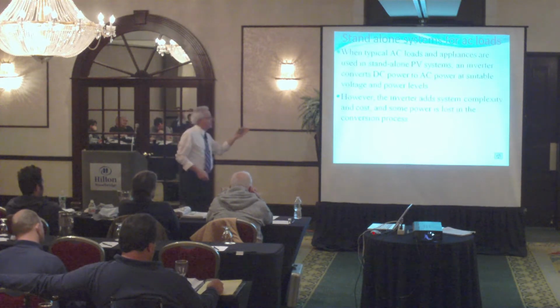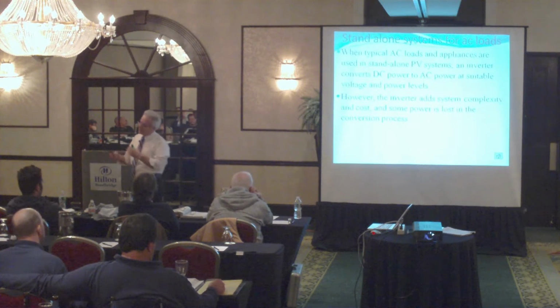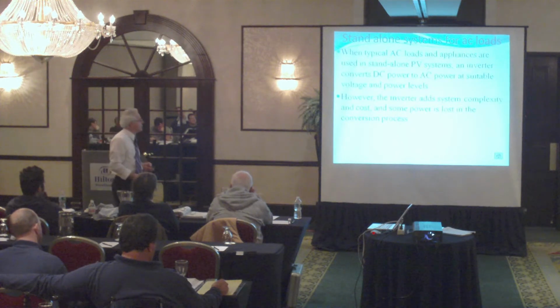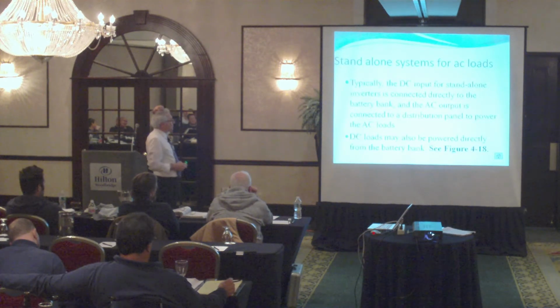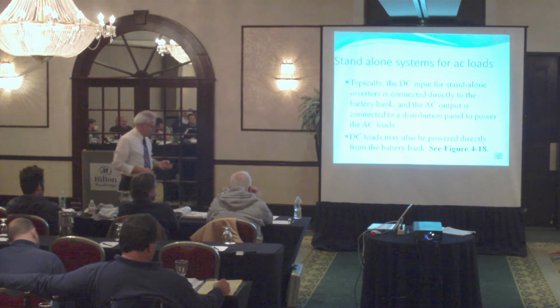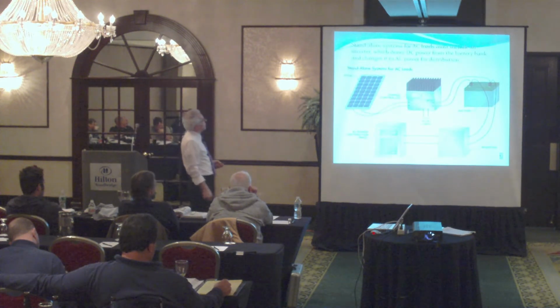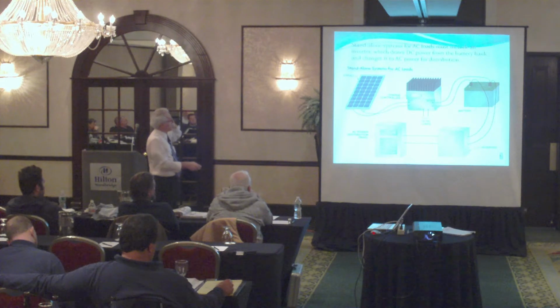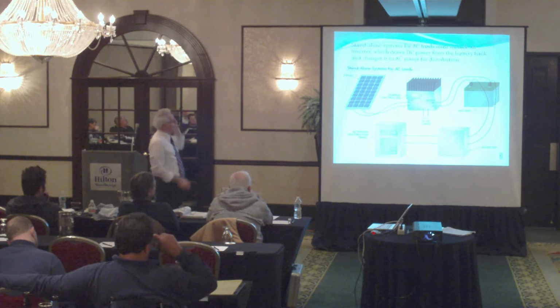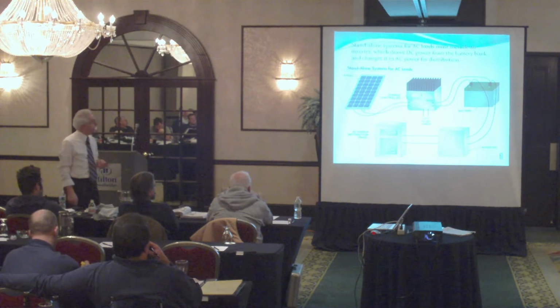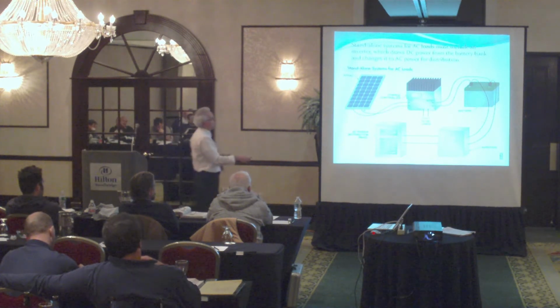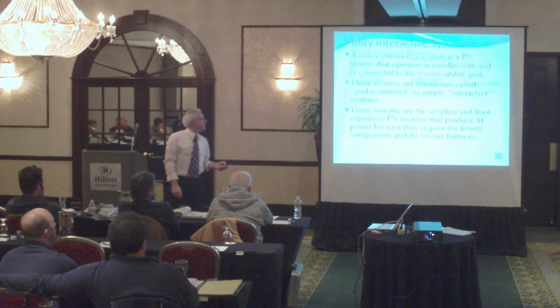Once you do that, you have a conversion process, so you have to consider the losses associated with the inverter. Look at this one, a typical configuration for that. This is your charge controller for the battery. Then from the battery, you take the DC to the inverter and to the actual distribution panel. A lot of the time, these combine together, so you're left with that.